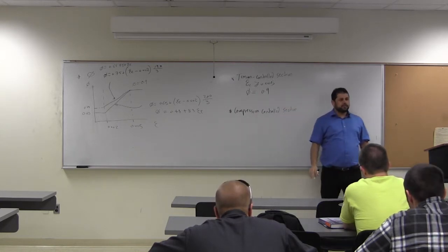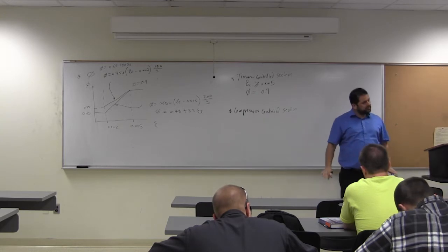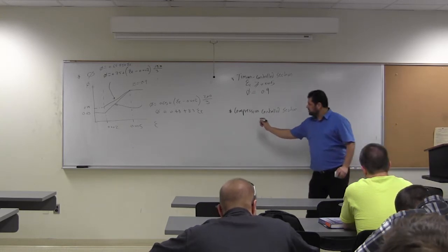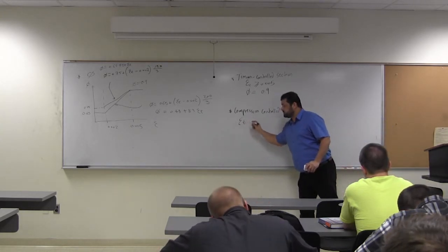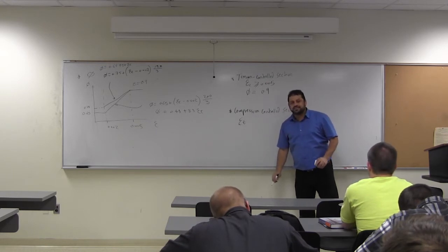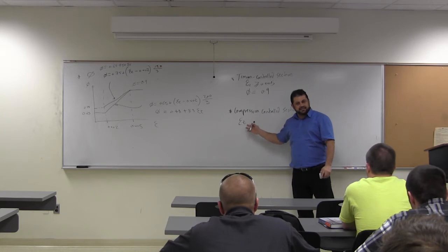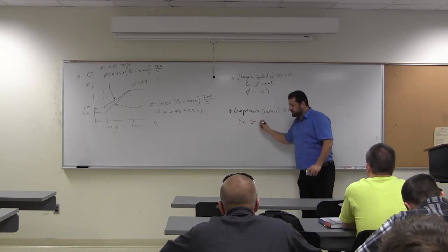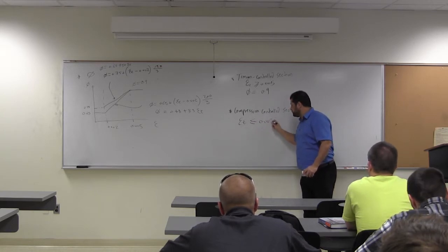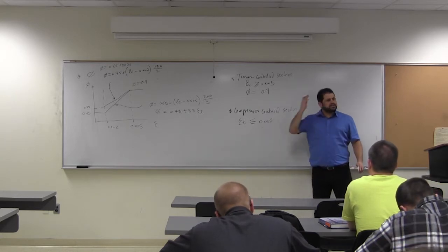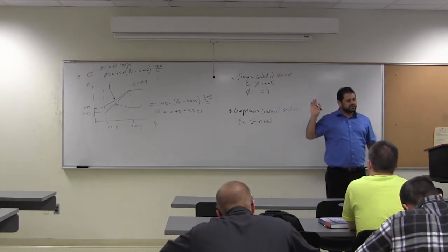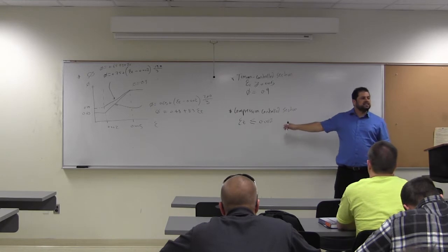We call it compression control. What do we know about it? Epsilon t is what? The steel did not yield. Steel does not yield at ultimate. It means the strain in the tension steel is what? Less than or equal to 0.002. Now this 0.002, guys, stick it in your mind. That's the yield strain of steel.